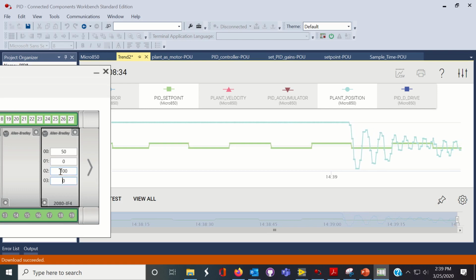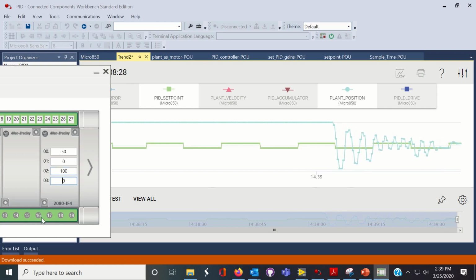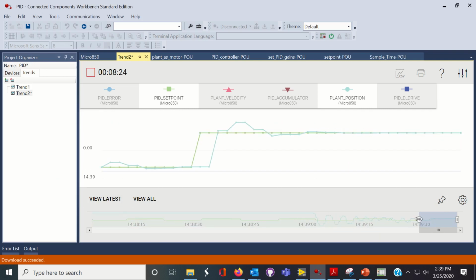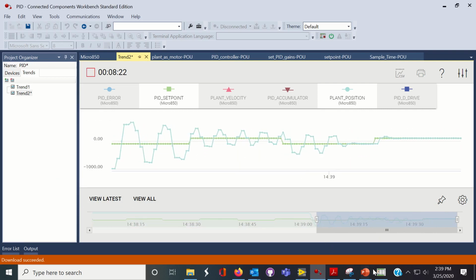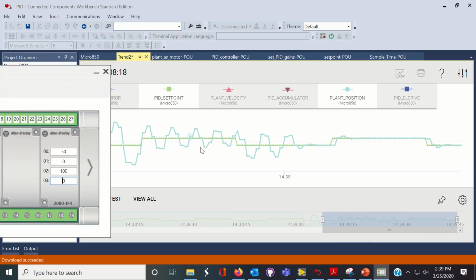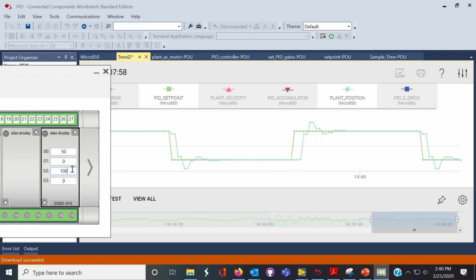We're going to go down to the third window, and you recall PID, so this is the D term. We'll add some derivative gain. Derivative acts as a brake. So if the system is moving quickly, the derivative tends to dampen it, to slow it down. And we've done pretty good. We've gone from an out-of-control oscillating system to something that's, well, reasonably good control.